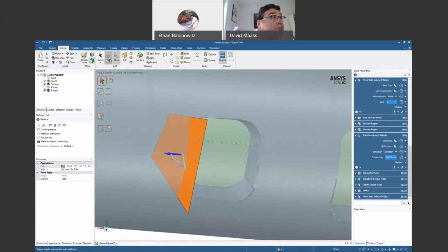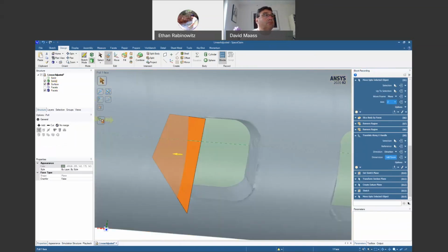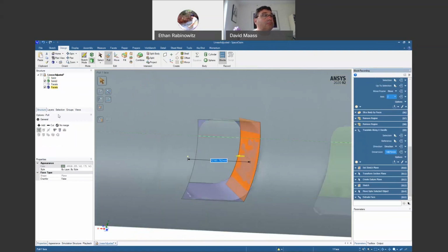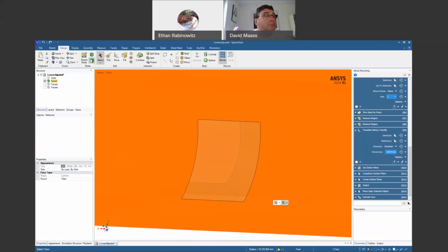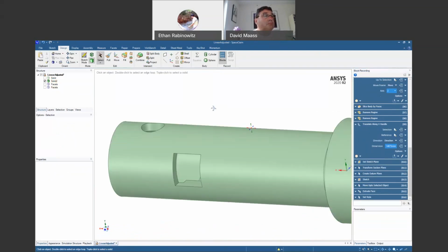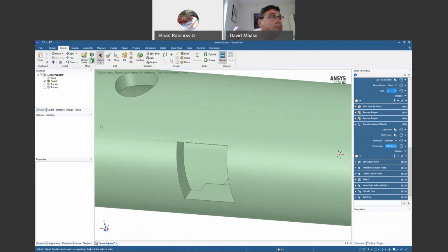And now we're going to switch to pull. Because pull is pointing to the left, to the right means it's going to automatically cut. So I should just be able to say up to, and I'm going to scroll my mouse wheel to pick one of the facets here. And there it's made our cut. And just so we have a good look at the model, let's make it opaque. And so there's our cut. It's gone through the different depths because we made it deep enough.